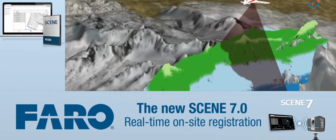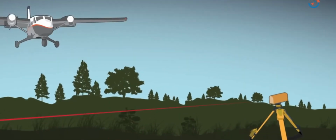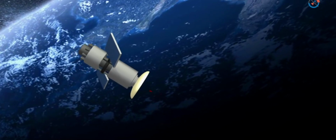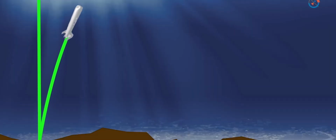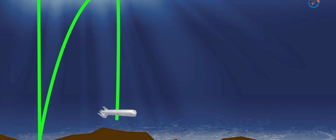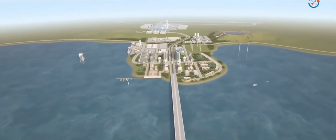Lidar comes in three varieties. Topographic lidar normally employs near-infrared light to map the land, while bathymetric lidar uses water-penetrating green light to determine seafloor and river bed elevations. Terrestrial lidar is effective for mapping buildings, natural features, and trees at ground level, and it is also valuable for creating 3D models of heritage sites.